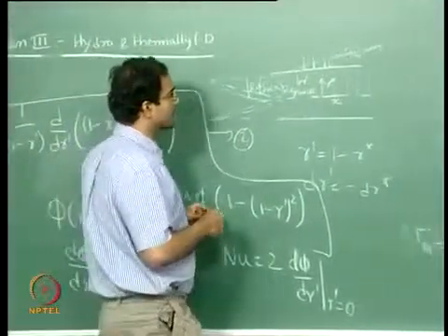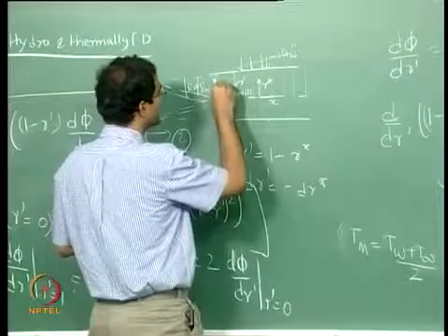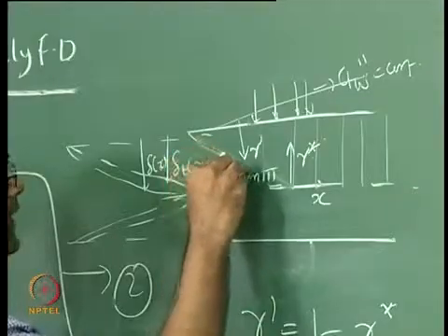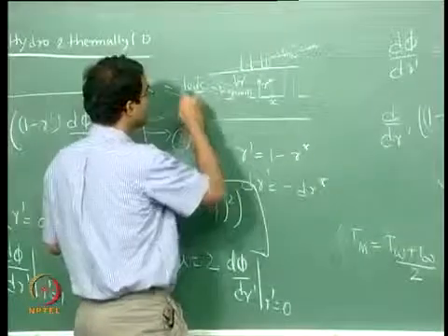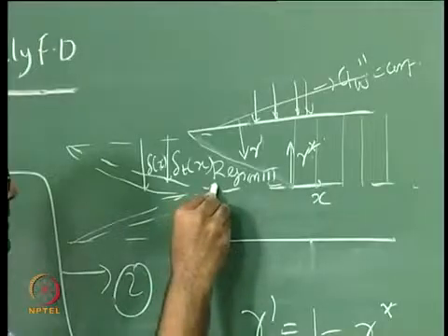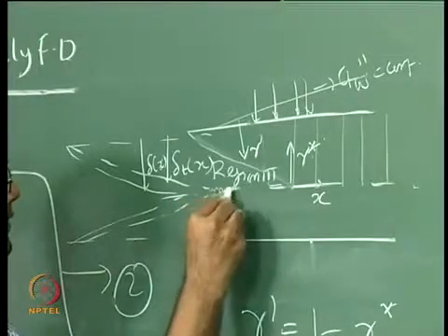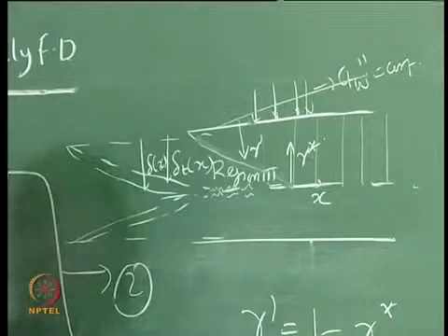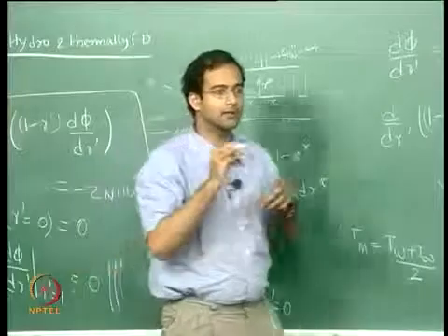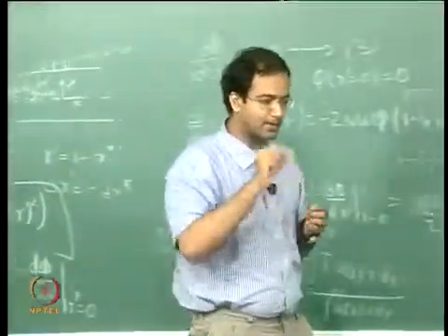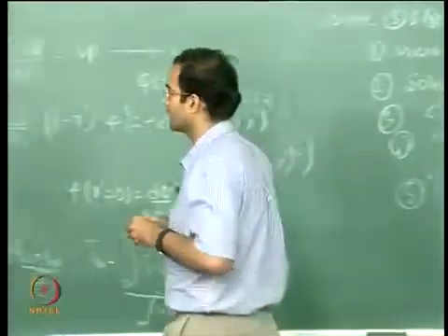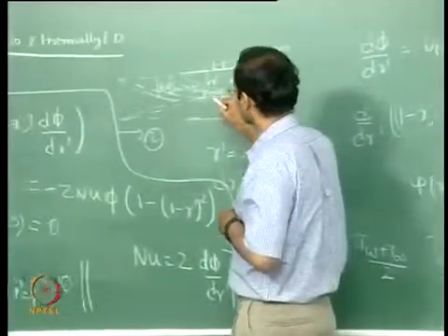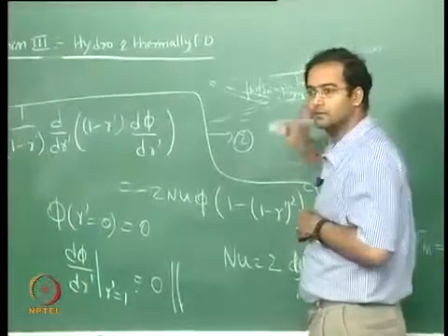So this will result possibly due to this dependence of the thermal boundary layer on the Prandtl number. When these two merge, there will be possible fluctuations in the thermal boundary layer. Okay. So it will not be exactly located and it will not be exactly merging at the center, but there will be some small fluctuations due to the property variation.